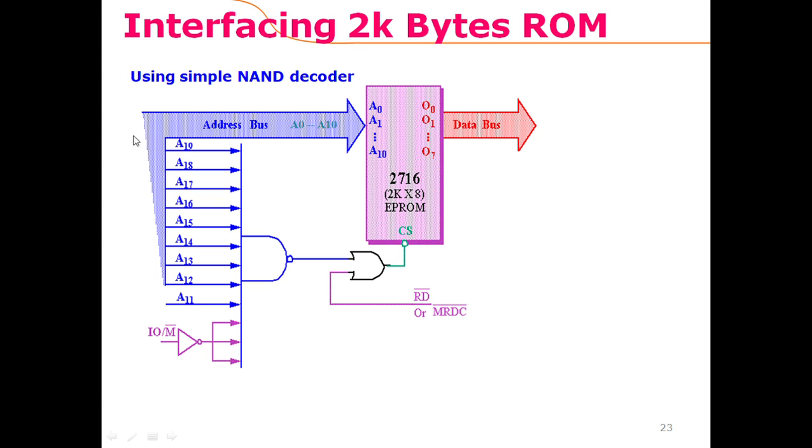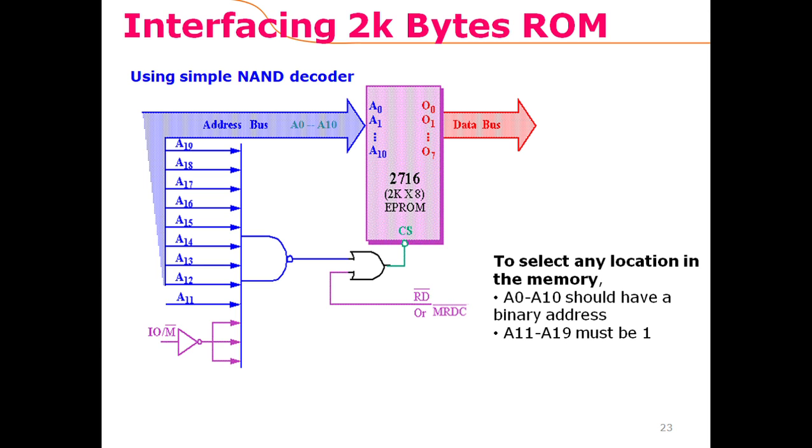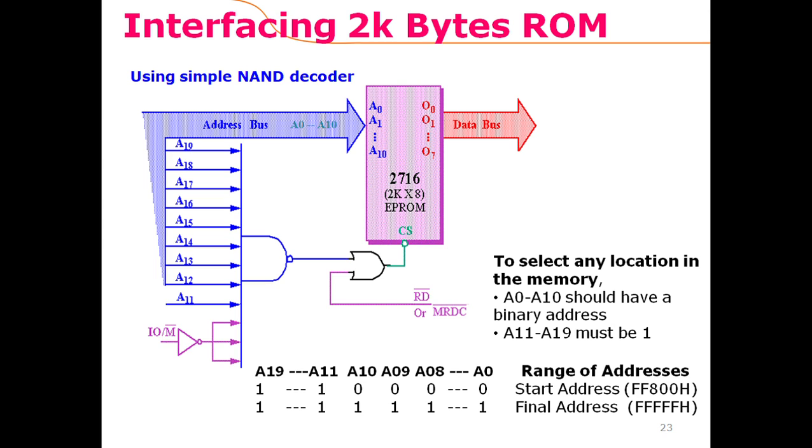out of the 1 mega addresses, which is the total capacity of addresses for the 20-bit address. So out of 1 mega addresses, we need to only decode the 4 kilo addresses. So that would look like this. Okay, so this is what I just explained, and here we also need to calculate the valid addresses.